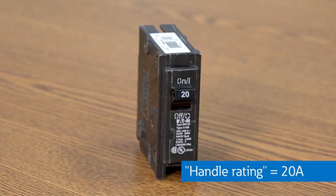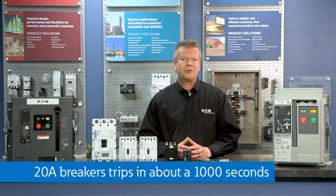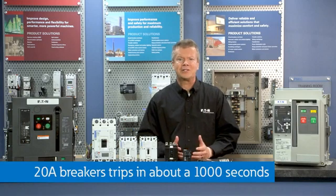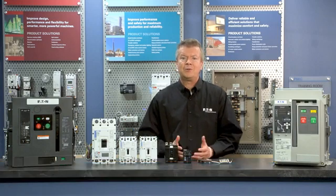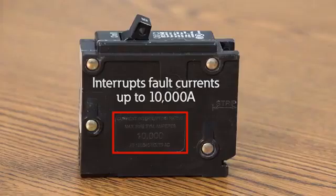Basically, a miniature breaker has a fixed trip curve like this one. A 20 amp BR breaker would trip in about 1,000 seconds for an overload slightly higher than its handle rating, but would trip in milliseconds for a fault condition. These breakers can interrupt fault currents typically up to 10,000 amps or 10 kiloamps.